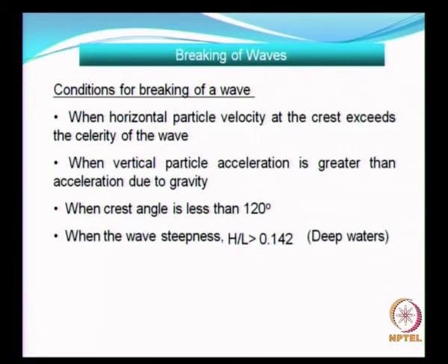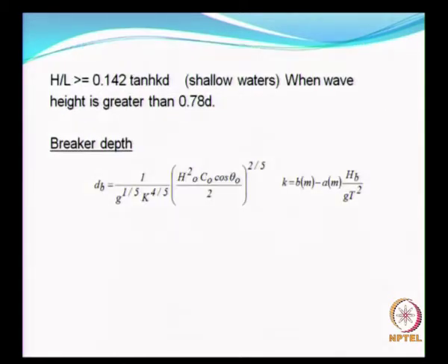It is not that popular, and when the wave steepness is exceeding 0.142 in the case of deep waters, and that 0.142 has to be multiplied by tanh kd in the case of other than deep waters. And finally, there is one more criteria, which is 0.78 times the water depth, that is when the wave height is exceeding 0.78 times water depth.